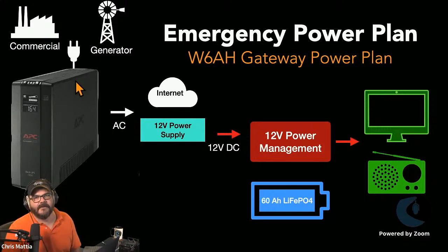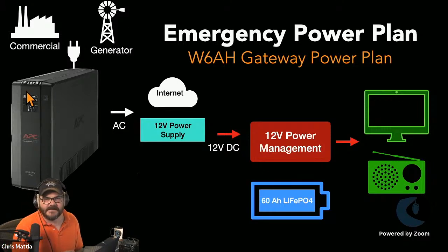At my place, I even have a second UPS that the first one plugs into. So I've daisy chained those so I can start hearing the alarms go off in series. And I know when the first alarm goes off, I've got so much time before the second alarm, given what the UPS is going to hold, for me to get my generator out if it's not already rigged and get it switched over to emergency power.